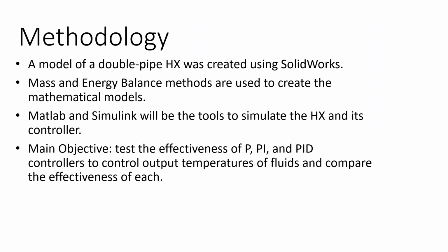Methodology: a model of the double pipe heat exchanger was created using SolidWorks as shown in the previous slide. Mass and energy balance methods are used to create the mathematical model, which will be presented later in the presentation. MATLAB and Simulink will be the tools to simulate the heat exchanger and its controller. The main objective is to test the effectiveness of P, PI, and PID controllers to control the output temperature of the fluid and compare the effectiveness of each, and use what we have learned in process controls to properly tune a P, PI, and PID controller in order to see which controller is best for our system.